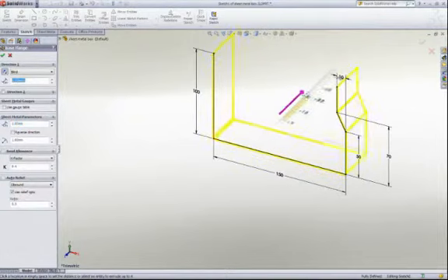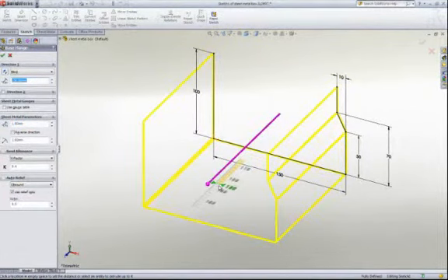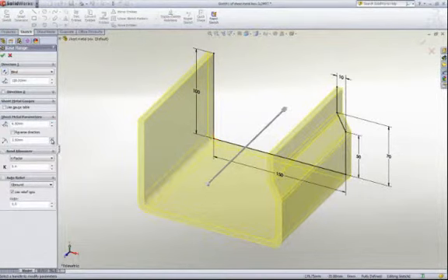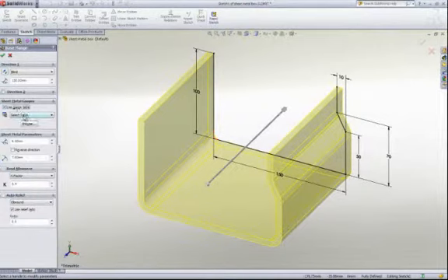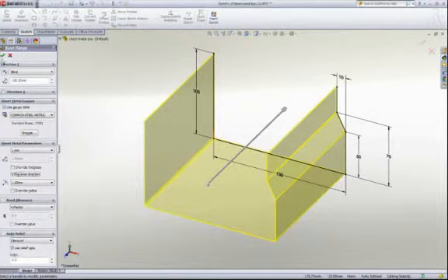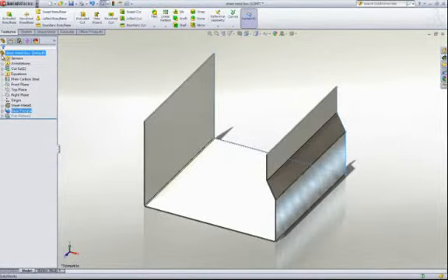In sheet metal design, we are often forced to adhere to certain requirements, such as standard materials and in-house standards for manufacturing and tooling. You need a simple way to make sure you comply with those standards. SolidWorks offers a customizable gauge table, which contains only the materials, thicknesses, and bend radii that are readily available in our shop, so there's no need to look it up each time, and you'll keep tooling costs to a minimum.